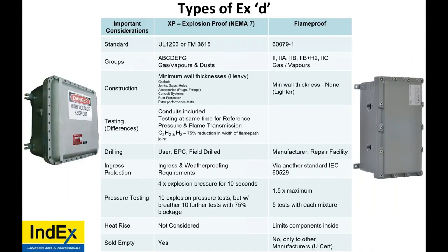So explosion proof is only NPT. Flame proof on the right can be NPT or metric. For explosion proof, it's a barrier gland every single time for a cable. When arcing and sparking equipment, in Canada, if it's EXD, it's always a barrier gland, full stop. There's also the barrier gland selection table, which the UK follows, which some countries follow, but the international standard has changed. This is a contentious issue.